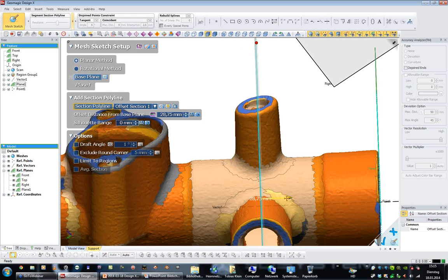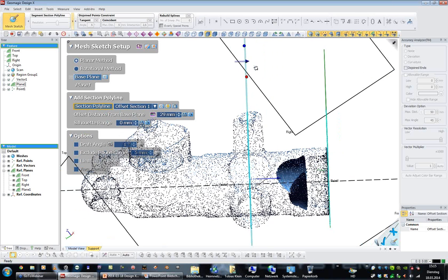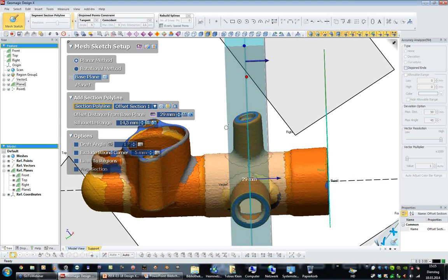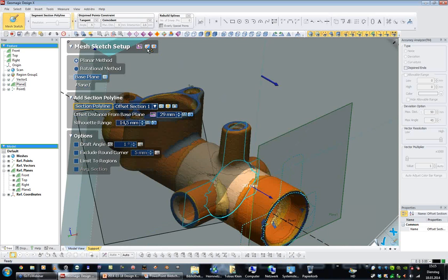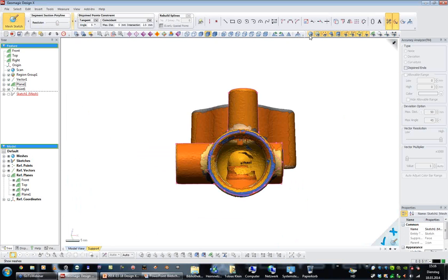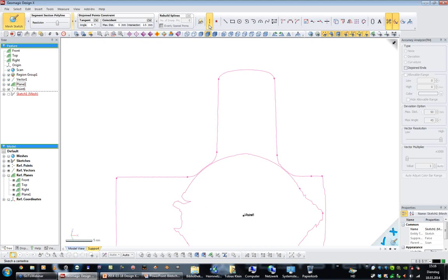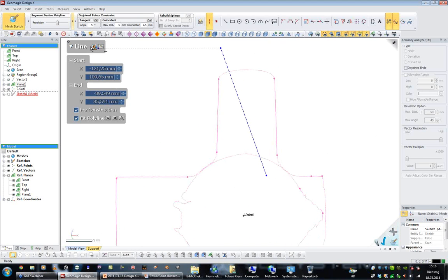At this position I am not sure where I'm cutting. Am I cutting at the widest position or not? So we have another arrow here. We can generate the silhouette from that feature and project the silhouette here. So in the silhouette I can just get a center line